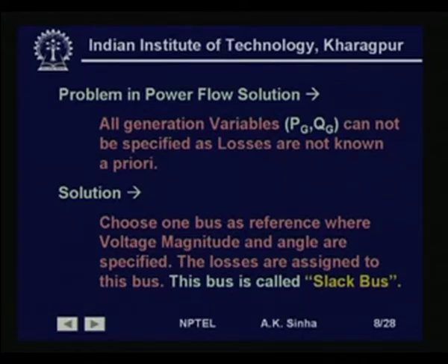To overcome this problem, we choose one bus as a reference bus which takes up all these losses, which we will find out after the solution. So, at one bus we cannot specify the generation.